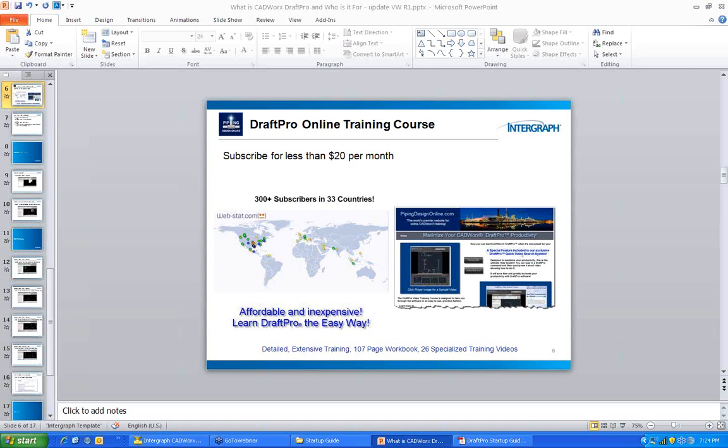Okay, so we have a question here. It says, is it possible to take a CADWorx file to Caesar directly? Well, when you're using CADWorx Plant Professional, yes, you can go to Caesar directly, but when you're using CADWorx DraftPro, no, you cannot. Okay, so what we've done is we've made available only the 2D engine within CADWorx to